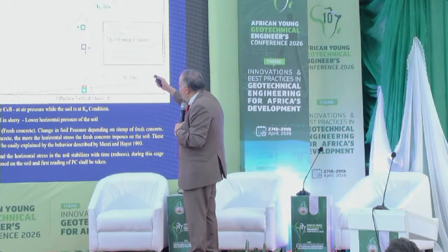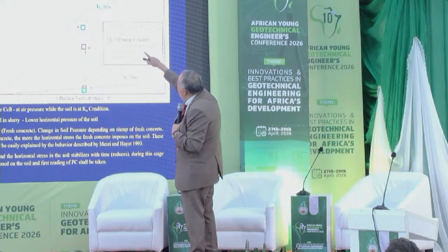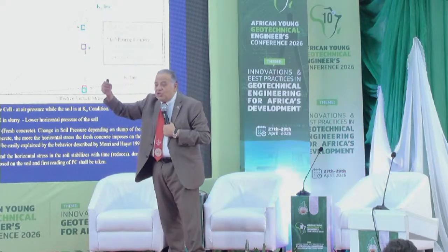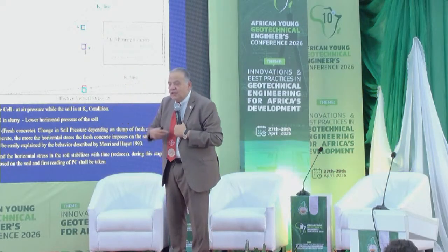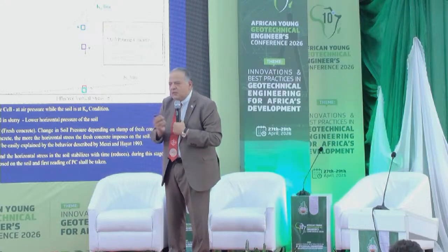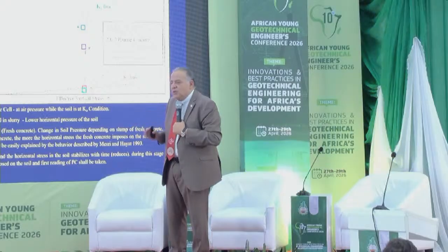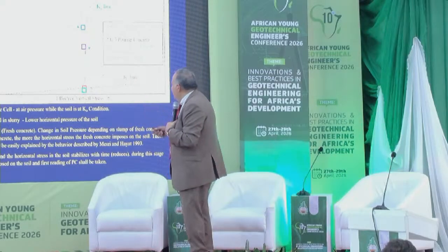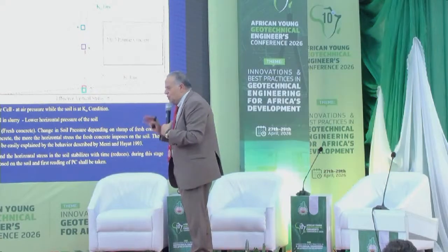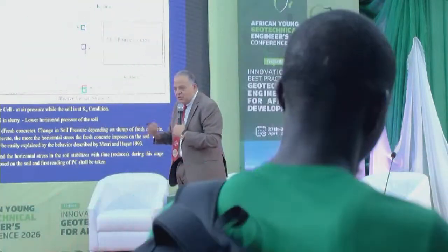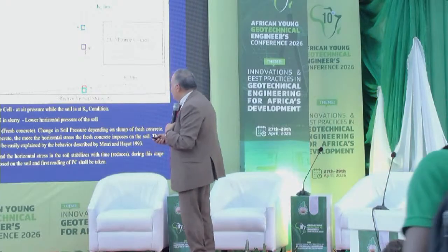As you can see, from 2 to 3, we jumped a little bit, because when the concrete is in a fresh state, it is not liquid, but it's not really solid. So it is pushing with a large pressure. And then when it's cured, the pushing on the cell will be a little bit restrained because of the solidification of the concrete.